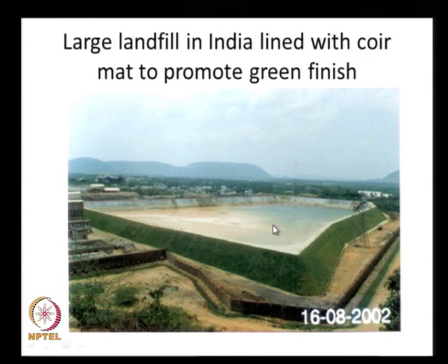And here we see the application of coir mat to give a green finish for a landfill, one of the largest landfills in the world, built in Visakhapatnam. The entire landfill was built above ground level, and unless it is given some natural finish, it may look very ugly. We want this entire structure to blend with the surrounding green hillocks and other features of this area. By covering the entire embankment with the coir mat, we could grow the vegetation, and now it looks very green and blends with the surroundings.